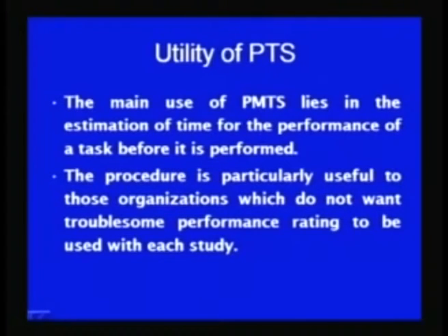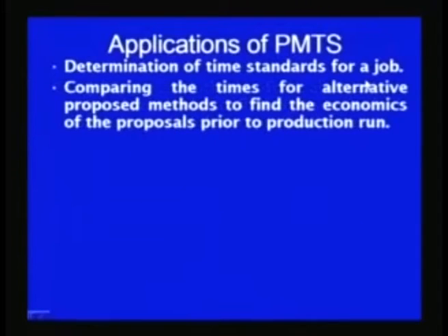In the time study, particularly the subjectivity associated with the performance rating of the worker during the time study is not found to be a very favorable point for those organizations where the time study is criticized very frequently. And in view of the very positive points associated with the PMTS, these are very extensively used in a variety of applications like setting the time standard for a job.